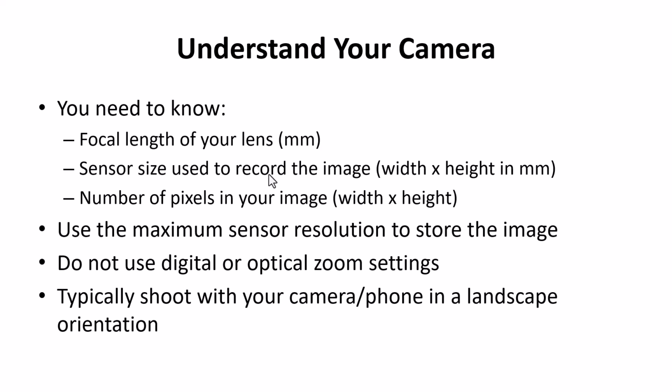Sometimes you can find out the specs for what is the size of an individual pixel on your sensor. It'll be a certain number of microns wide and high, and most sensors on cameras are square, so the width and height of that individual pixel on the sensor will be the same. And then if you know the number of pixels, number wide and high, which is a pretty easy thing to find, you can multiply the size of an individual pixel by the number of pixels and recover this width and height. So you're going to need to know that.